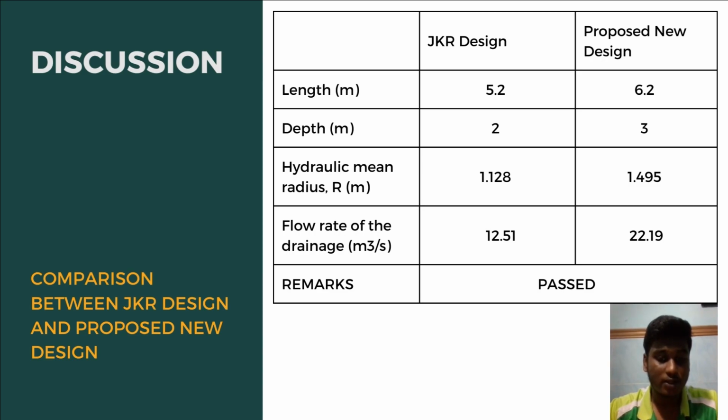Okay, so the drainage friction slope was calculated and we got 0.0041 meter. As a result, Manning's equation holds true for a constant water flow rate through a channel with a constant size, shape, and roughness of the slope.